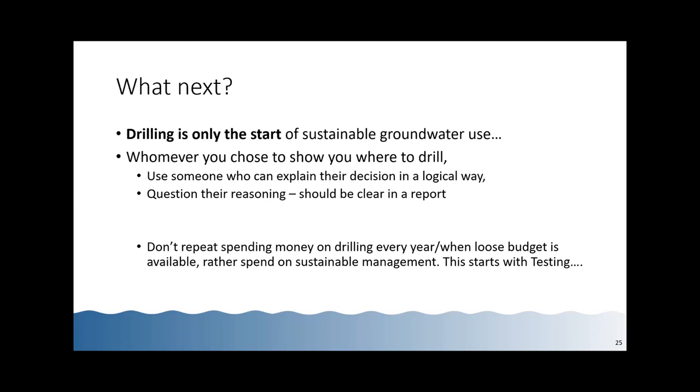Drilling is not a process that you should repeat every year when the budget becomes available. It's not a hit and miss story. It's actually a once-off project where you might have to drill more than 1 or 2 boreholes, and thereafter you have to spend your budget in testing and monitoring that hole. If you have more questions, I'll be at the end of this slide. I'll be willing to hear them, but I'm going to hand over now to Kes Murray, who's going to tell you more about the very important next step of testing that borehole.